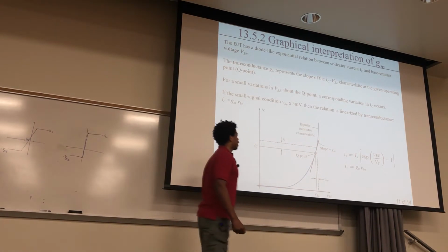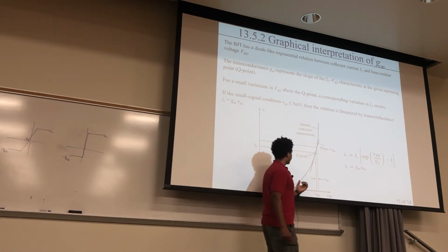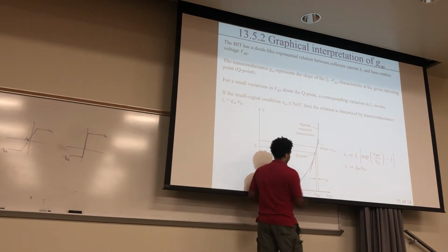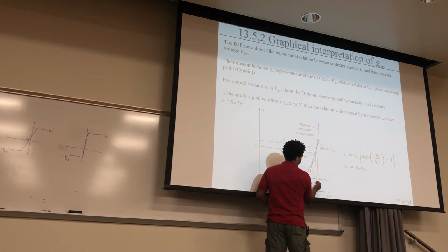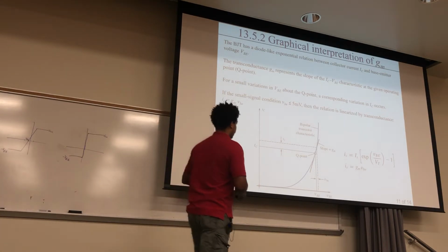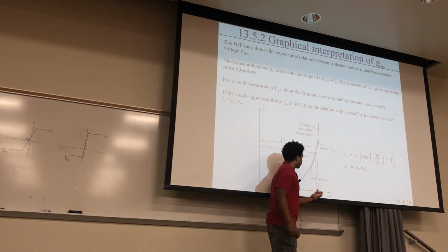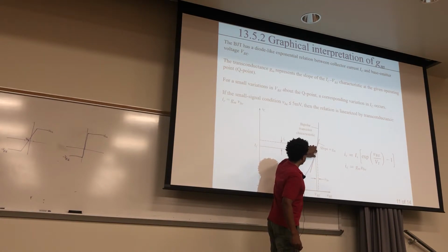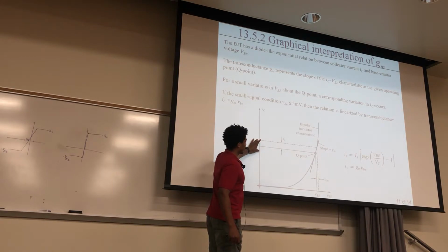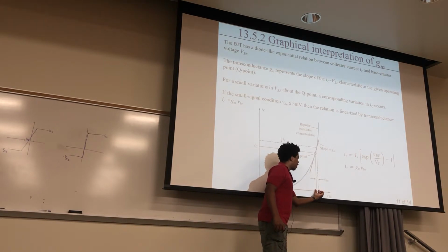Just like the diode, you have your Q point, your quiescent point right here. That's where you set your DC up, and then you do your small signal variation about that. If it's within a certain value, like about 5 millivolts, if this BE goes as high as 5 millivolts back and forth, then it linearly transfers to the current without distortion, within that small range of values.